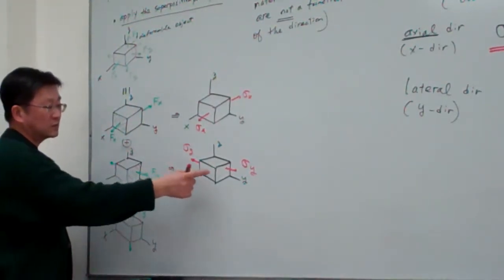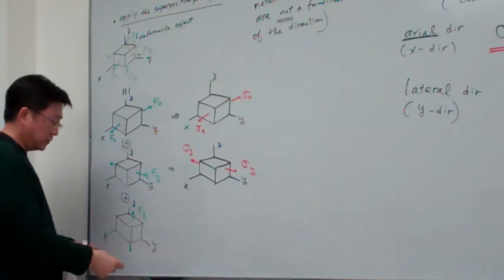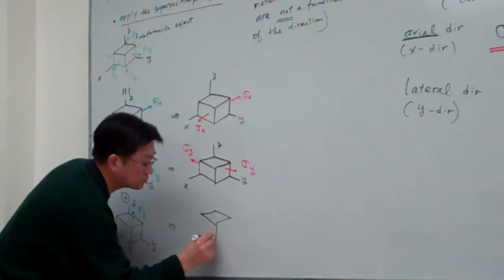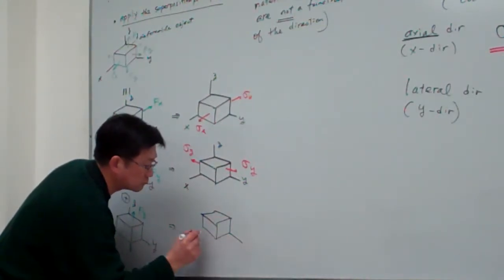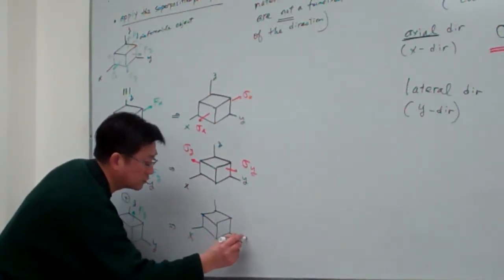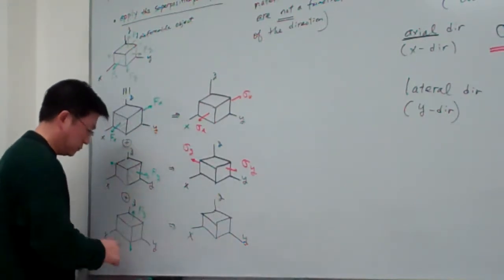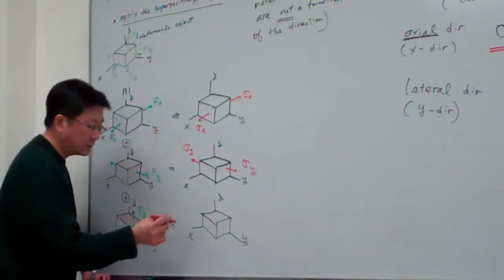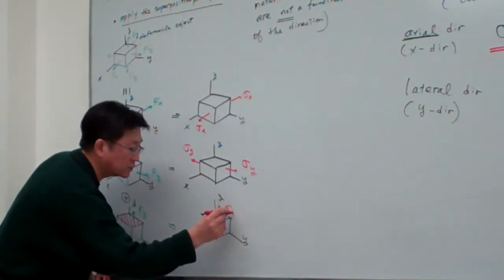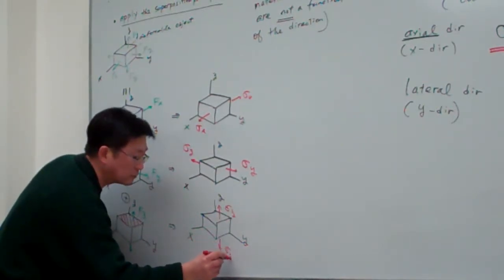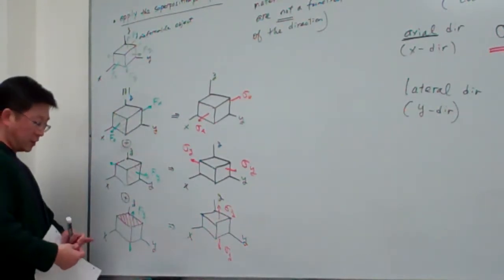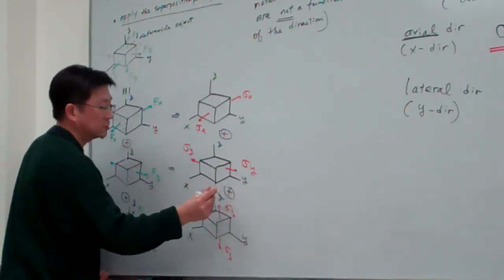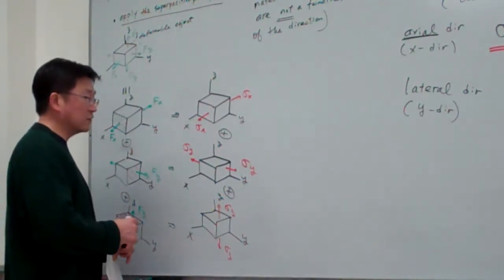So right now for this case, y is the axial direction. And now for the third one, x, y, z. And then again, divide the force Fz by the area, so that will correspond to sigma z. And keep in mind, the three things are still under the superposition. Okay, so now we do these things individually.